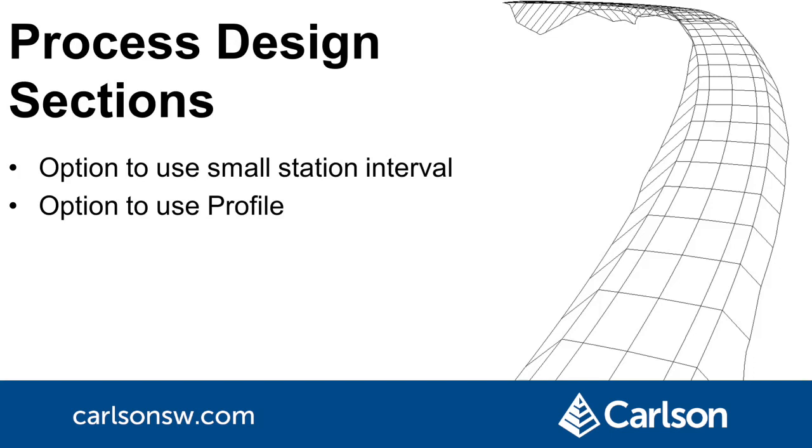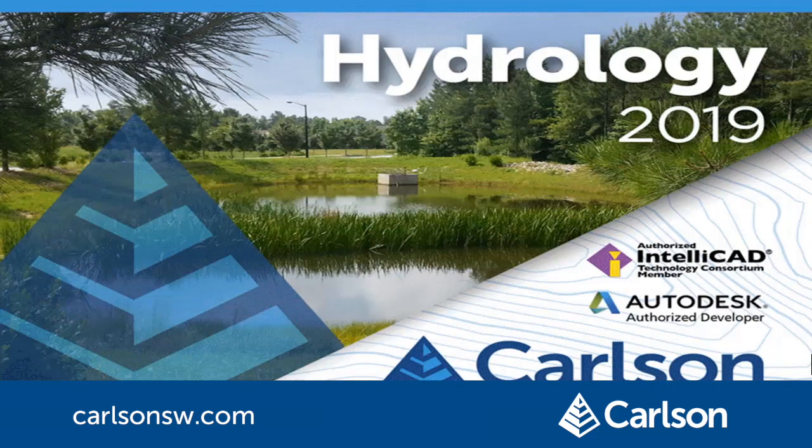Process design sections is for creating a road from cross sections. Now the program has an option to interpolate stations at a smaller interval than the source sections. And there's a new option to use a profile to set the elevation for the interpolated stations. Next is Carlson hydrology.